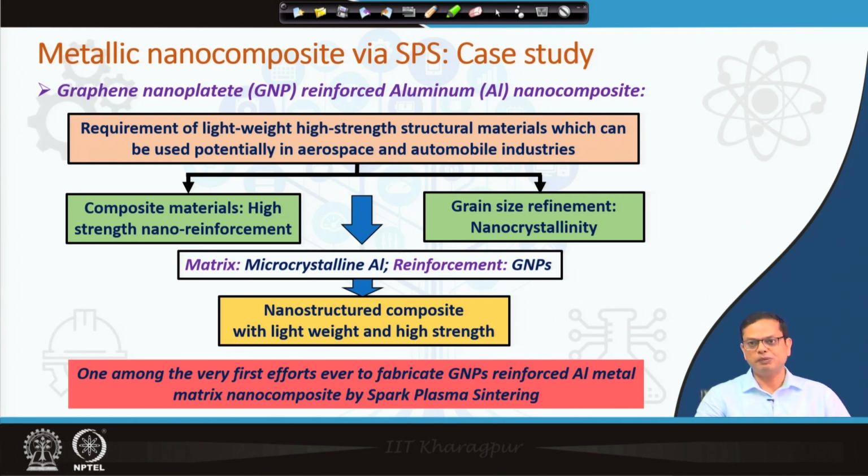So, hard nanoparticles would lead to extremely good composite strengthening. First of all, they are extremely hard, so that will obviously give you a better composite strengthening effect. Secondly, because of the nano size, the number density of those particles will be very high, even if a small amount or volume fraction of this material is used.